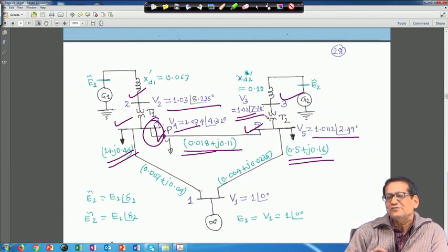As usual, pre-fault also, whatever number of machines are there, accordingly we will reduce, right. Similarly, for the during fault and post fault conditions, and after that we will write down the power equation, then we will write the swing equation during fault and post fault condition.